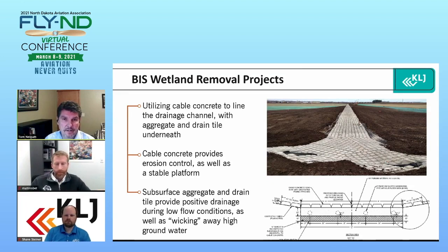So in these areas where we do have high groundwater, as we talked about earlier on the runway, we can actually wick the moisture and the subsurface drainage out of there. So while it looks dry on top, typically what's happening underneath here is there's water still running through these underdrains or these drain tiles.